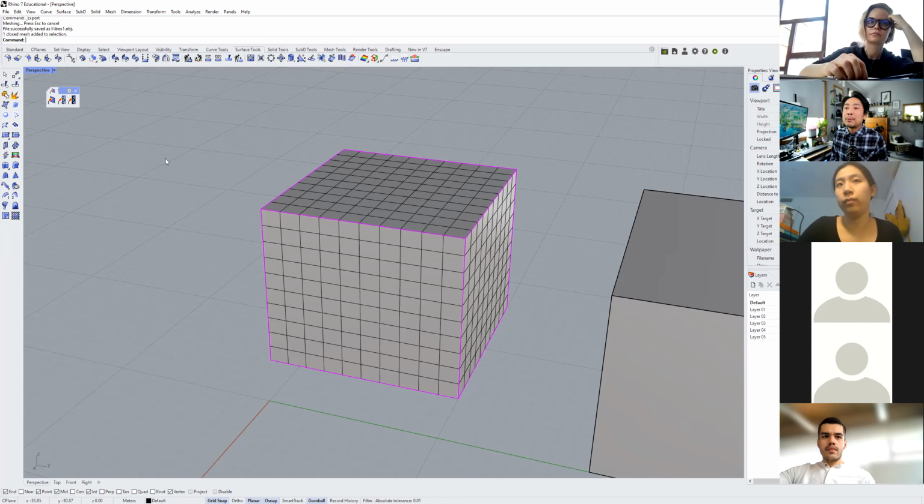Okay, so every time you move an object from the digital space to the screen, or to 3D printing, or to laser cutting, you need to turn an object from whatever form it takes, whether it's NURBS, a solid, a sub-D surface, everything goes out to the physical world in mesh forms. So you need to understand that this is the rawest form of a geometry representation. Everything will end up as a mesh, whatever it is you begin with.